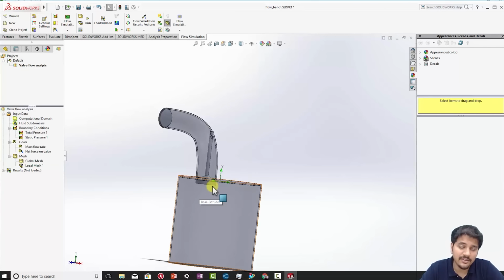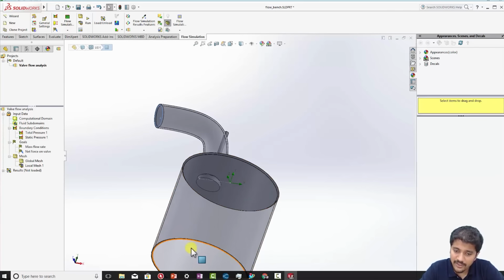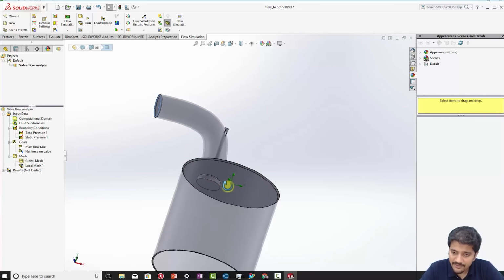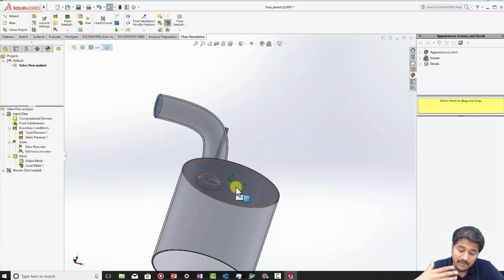And now, as far as the CFD simulation is concerned, I'm just setting up a steady state simulation here. So this is my inlet, right? This is my outlet, and I set up the valve in such a way that the flow is just going to flow around it. Now, since this is a project, I'm not going to give you a detailed walkthrough on how I set it up. You have to figure it out on your own.